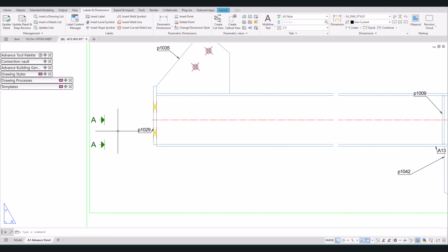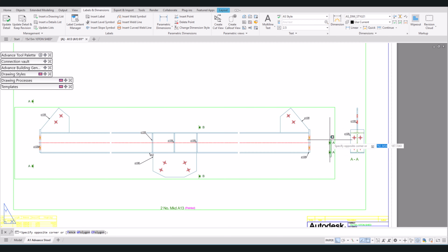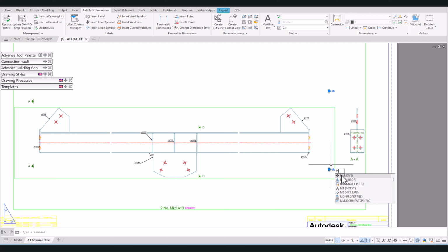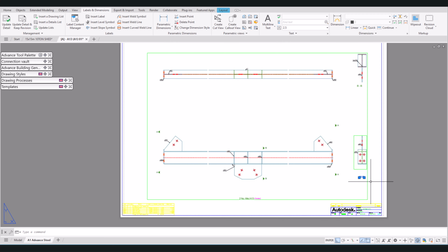Right, then you've got these section labels. Let's push them up and then pull them in somewhere there. Select both of them, pull one up, pull one down, use the move command, and then we pull them in. Guys, remember all the AutoCAD commands are available in Advanced Steel. It's basically AutoCAD. That's why it's easy to use, especially if you've been using AutoCAD.